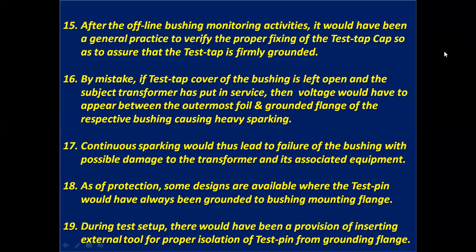By mistake, if the test tap cover of the bushing is left open and the subject transformer is put in service, then voltage would appear between the outermost foil and grounded flange of the respective bushing, causing heavy sparking. Continuous sparking would thus lead to failure of the bushing with possible damage to the transformer and its associated equipment.